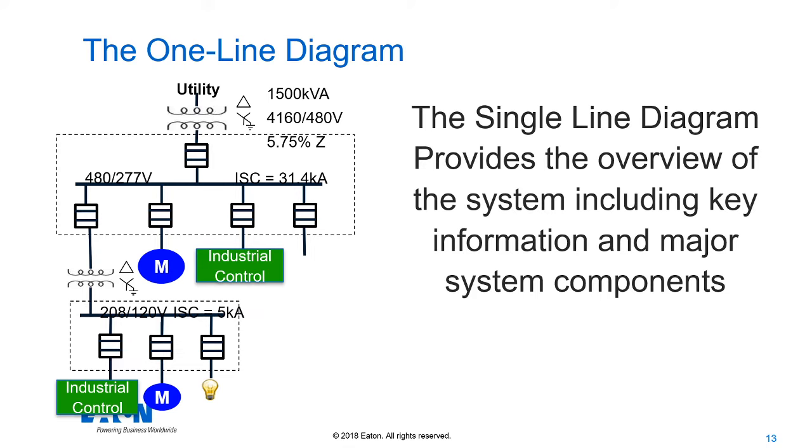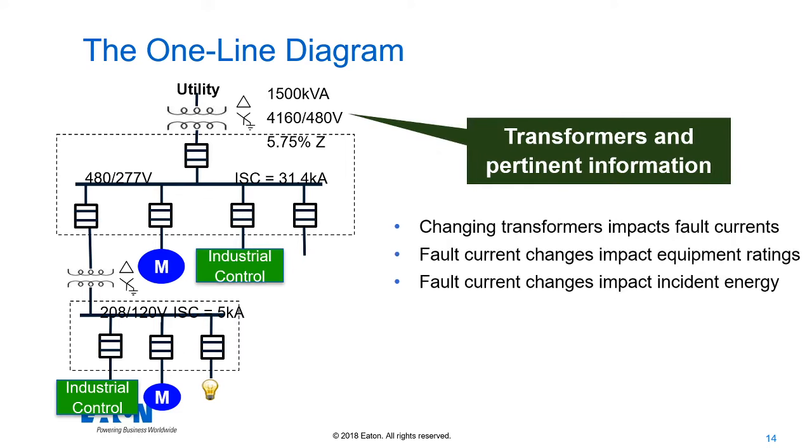So the secondary of each of those is really a critical piece of the pie. And then you'll have the kVA, the voltages on the primary and secondary, and the percent impedance. Obviously the kVA is really important. Sometimes you'll have a complicated kVA with OA, FA ratings, where there are fans or oil cooling, etc. But you'll have a lot of information with regard to that transformer.